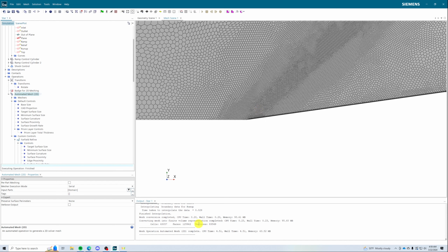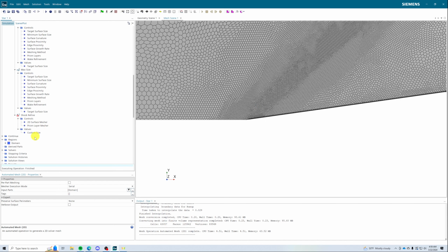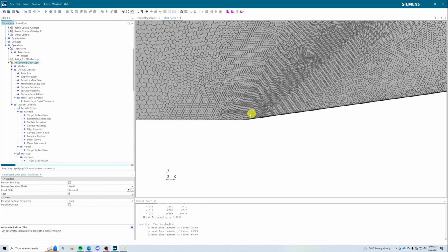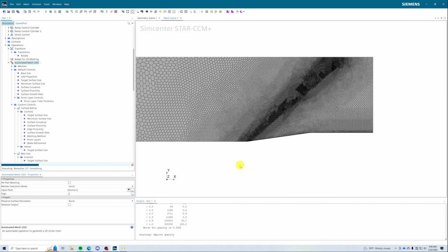Okay, there we go. So we're up to 43,000 cells at 50%. I'm definitely glad I didn't do 10%, mind you. But let's be a little bit aggressive and go down to 10% or 20%. These are going to be 1 millimeter cells. These are going to be bigger than the shockwave, for darn sure, but they're going to be smaller than anywhere else.